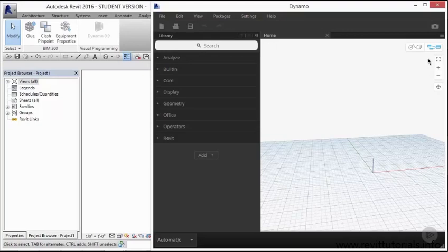When you hover your mouse over the icon that is currently selected as blue, it should say Enable Graph View Navigation, and then hover over the one just to the left of it. And what you'll see is that it says Enable Background 3D Preview Navigation. Now, the 3D preview correlates to this grid that you see in your workspace. In order to truly understand what these two settings are doing for us, we have to first drop in a component as if we're building a definition.